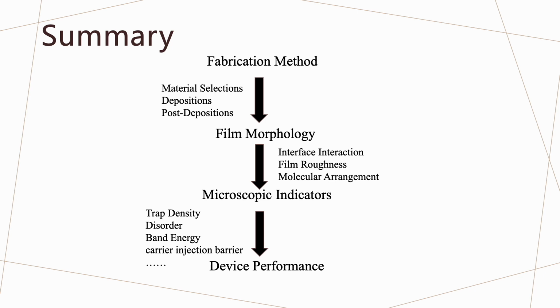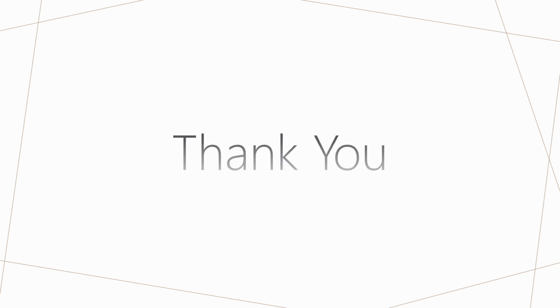The film morphology will influence the microscopic indicators like the trap density, disorder, band energy, and carrier injection barriers. And these microscopic indicators will influence the device performance, including the operating voltage, threshold voltage, on and off ratios, etc. Thank you. That's all.